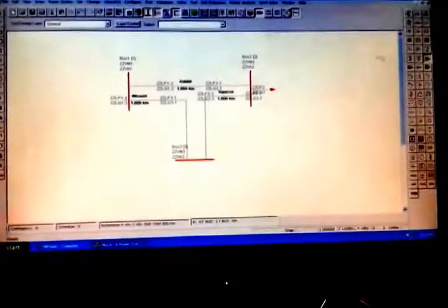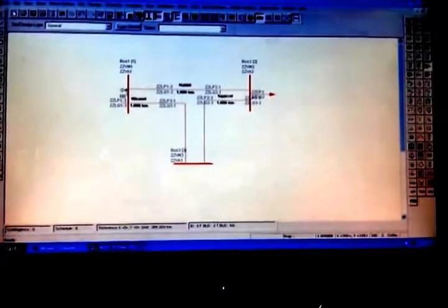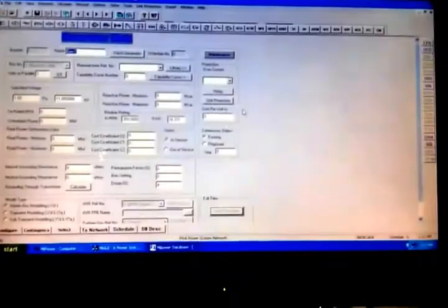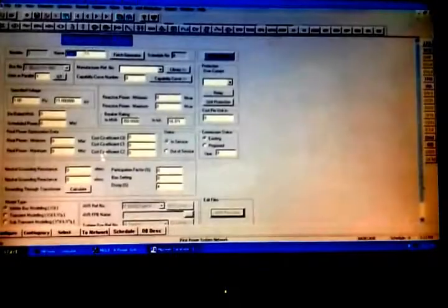Select generator. So if you see the generator, it has a different direction. So rotate twice so that you get the required direction and place it on bus 1. Then give OK. Now you get this generator data. Here also you have a library. So select the manufacturer reference number.